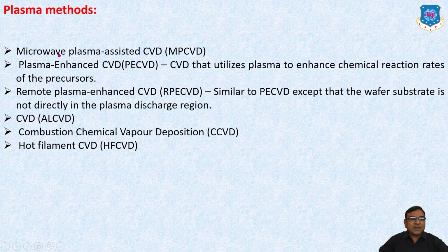Plasma methods. Microwave plasma assisted CVD, that is MPCVD. Plasma enhanced CVD, PECVD, is CVD that utilizes plasma to enhance chemical reaction rates of the precursors.